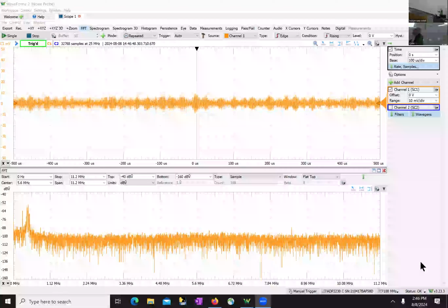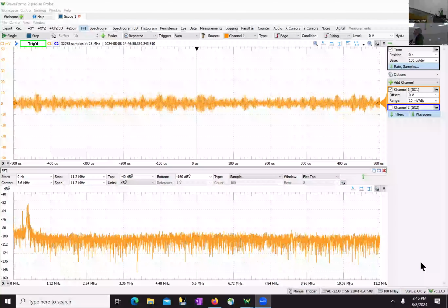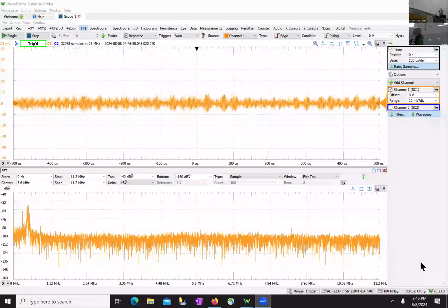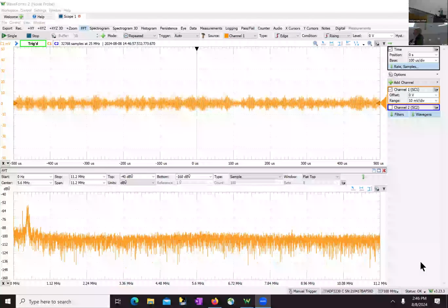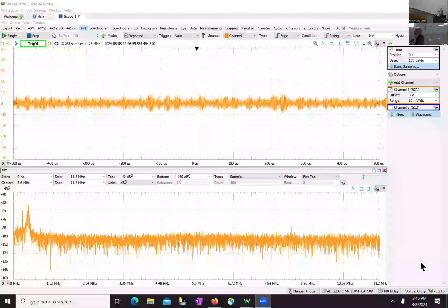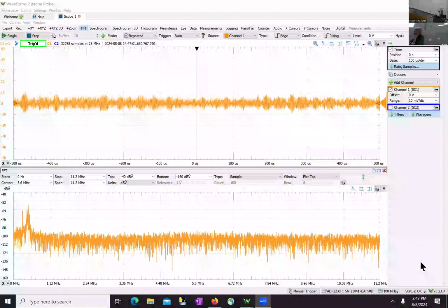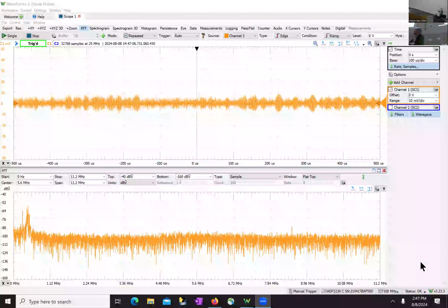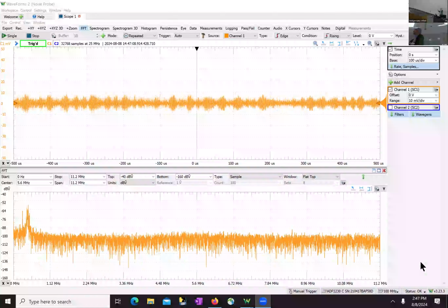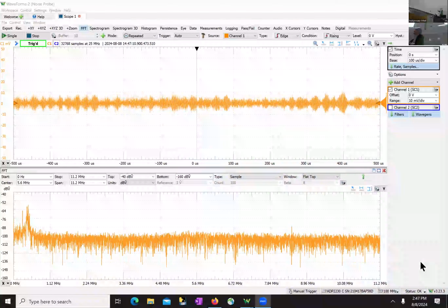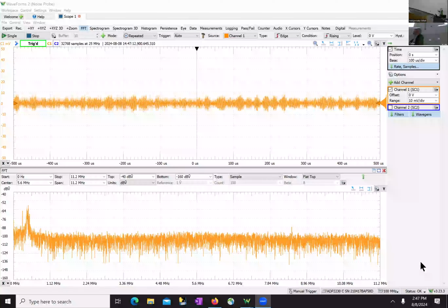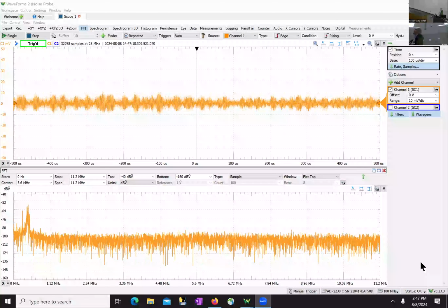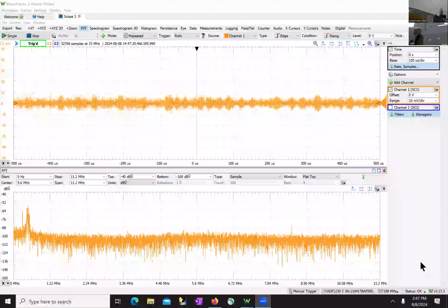Then on top of that, you also have ionic noise. Because we're applying a voltage and we have moving ions, we also have yet another form of electron motion in the nanopore, and that adds more non-coherent or non-periodic noise. So the thermal noise of the resistance is random or non-periodic, and the ionic noise in the pore is also random and non-periodic.